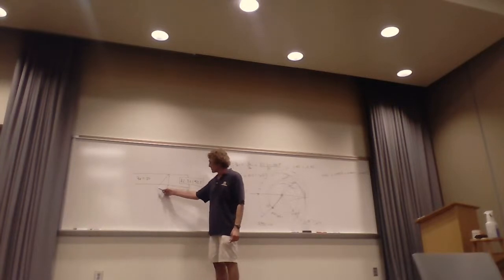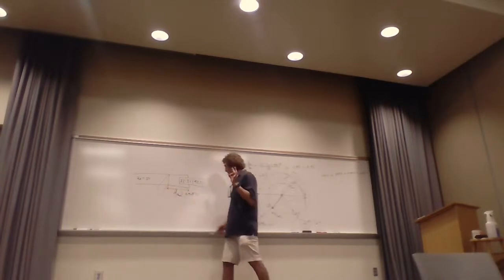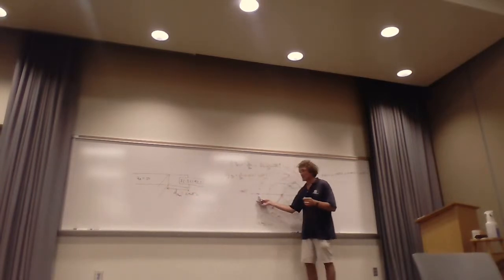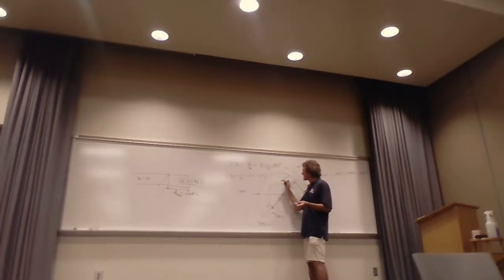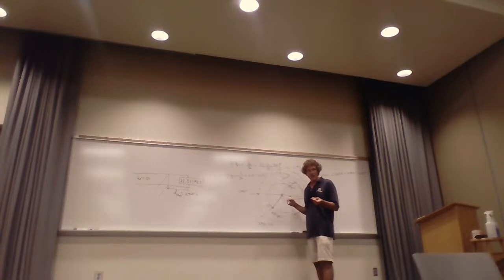Open circuit stub has an impedance of infinity and an admittance of 0, right? Even when we normalize that admittance, it's still 0, right? Now, the 0 point is right here, correct? Now we want to move on this rim until we hit 0.8, right?